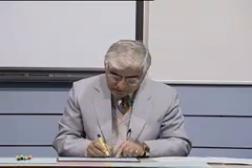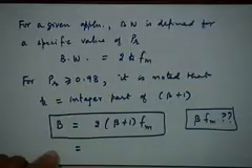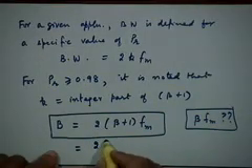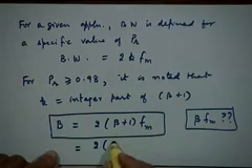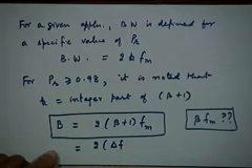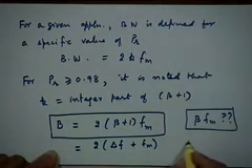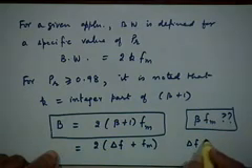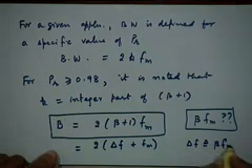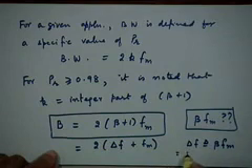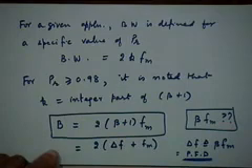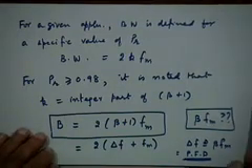So therefore you can also write this formula in a different way, namely twice beta times Fm, let me call this delta f, plus Fm, where delta f is defined as beta times Fm and can be interpreted to be the peak value of the frequency deviation, the peak or maximum frequency deviation.